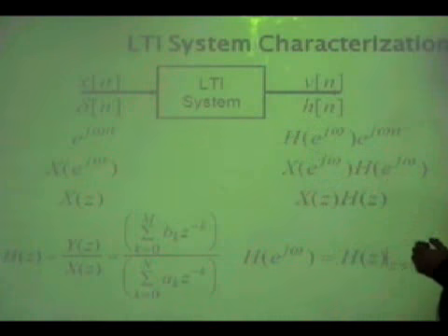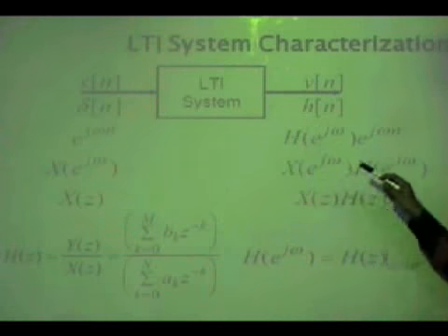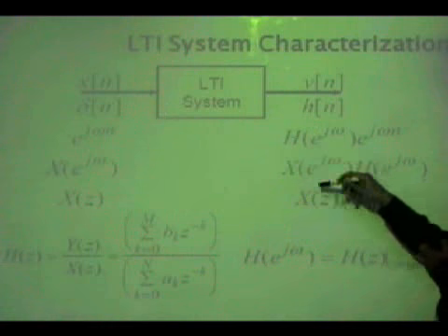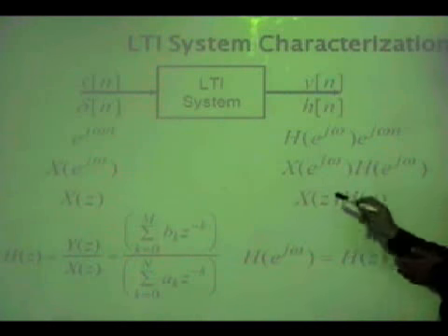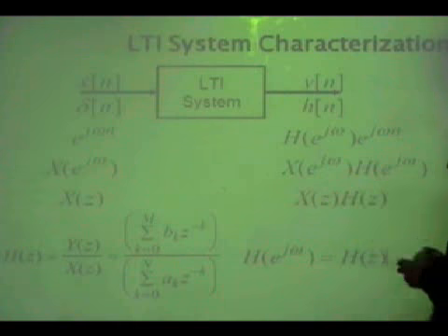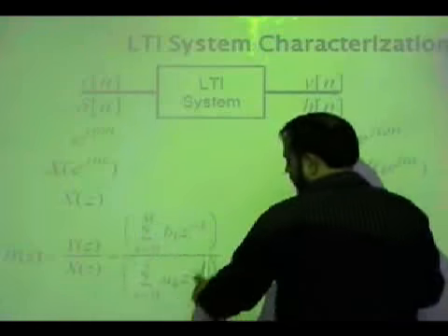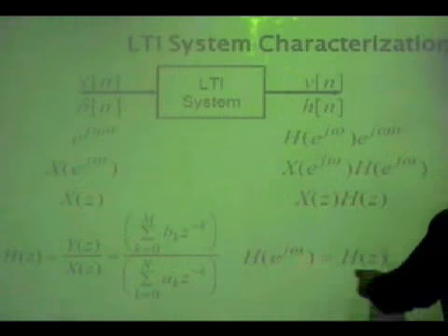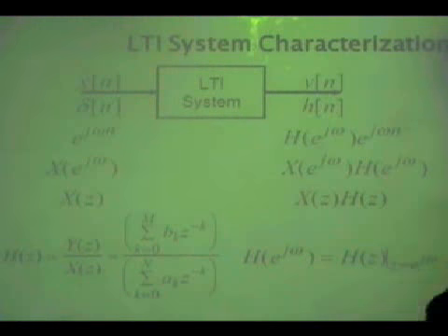We have learned that convolution in time is multiplication in the frequency domain. So the convolution here will look like this, and the same is true for the z domain. And this is how you compute H of z from the difference equation. This is how you write it, and if you replace z by exponential j omega, it will give you the Fourier transform.